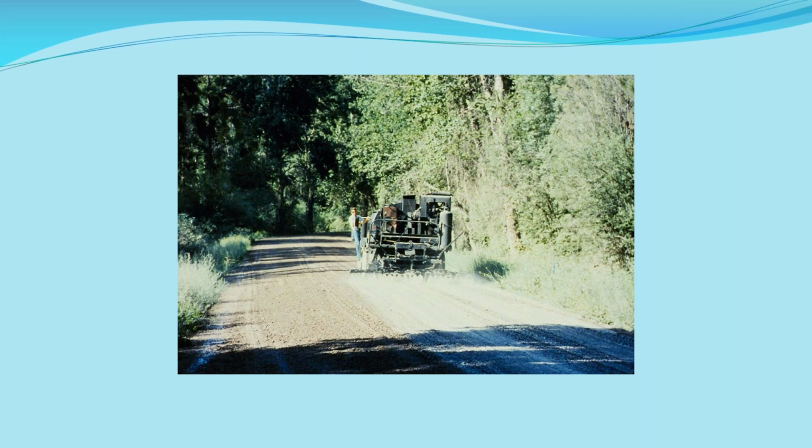After we did the treatment, we came back in with a roller again and recompacted the material and made sure it was compacted really well. Then we took the roller out and washed the magnesium chloride off of it. Generally speaking, if I had fully compacted this roadway, we would have been shooting probably about an eighth of a gallon per square yard, and then shot it in 4 shots instead of 2 shots to get it up to that half gallon per square yard.